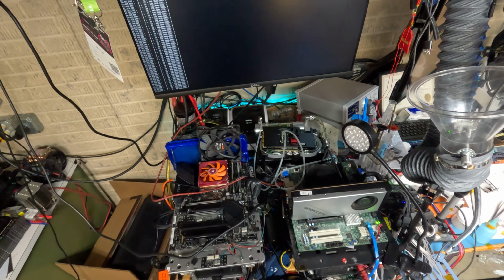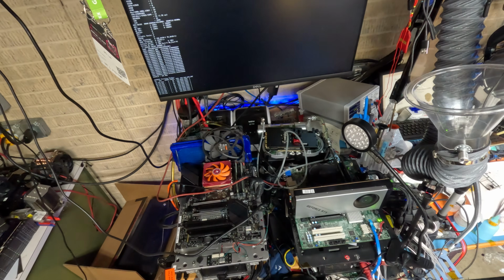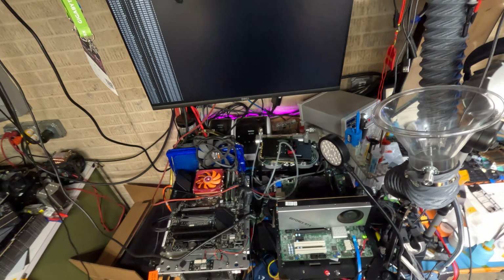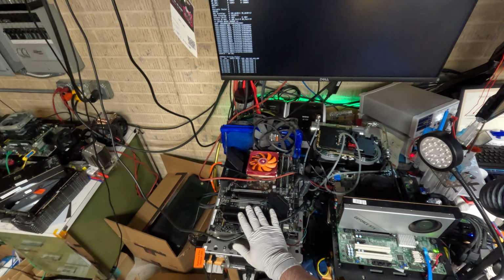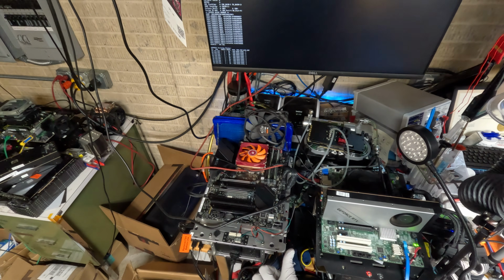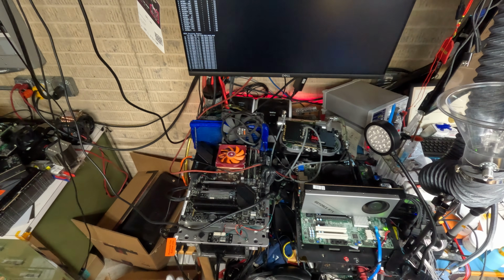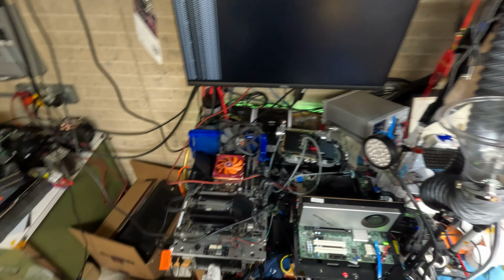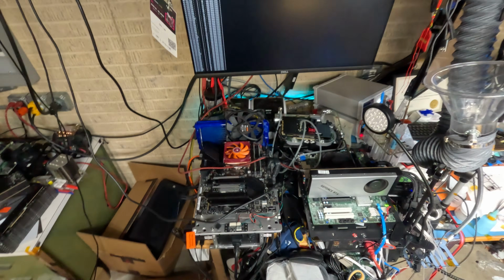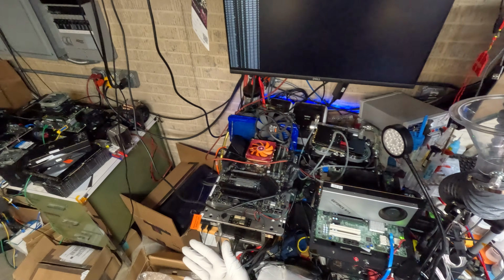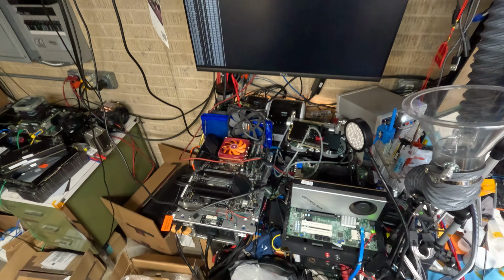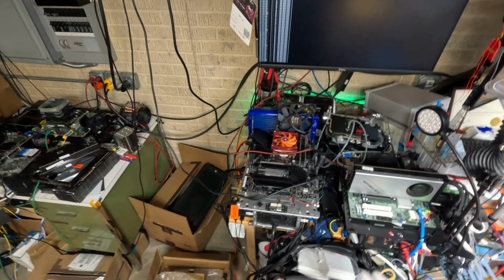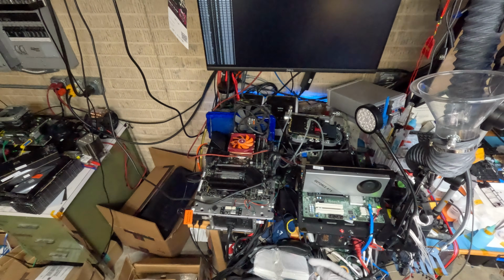And that's only because I had recently replaced a few memory modules. So when I initially received this card, it passes memtest Vulkan. I put it on ComfyUI, I see an issue. I say, okay. Then I load it on NVMT, and this was a few days ago, and I saw a few memory modules that are pretty bad, and so I replaced those. Put them back on ComfyUI, and it works fine. And I tested it overnight, and I issue the customer an invoice, and I send it back, and it's all good. Customer gets it, immediately starts having issues again.